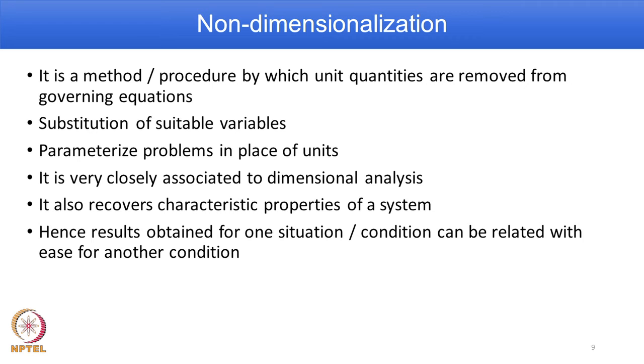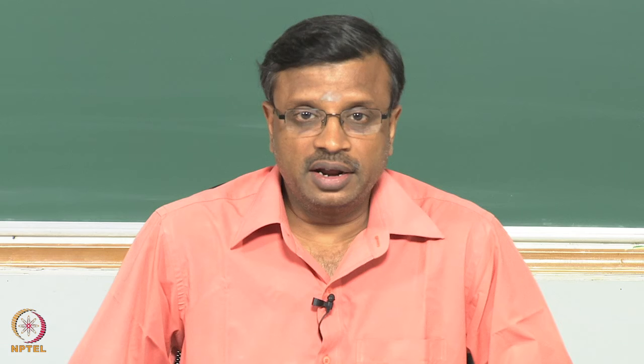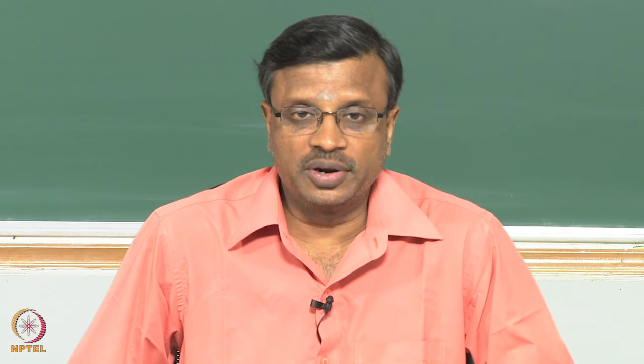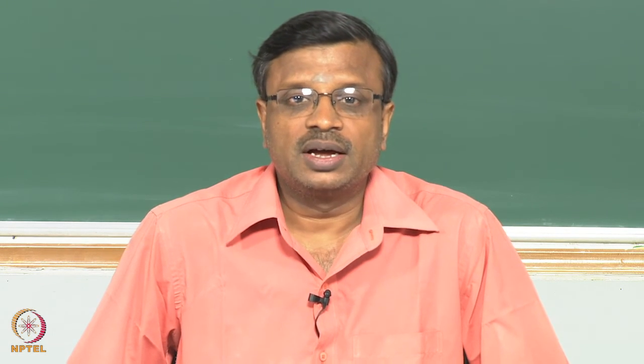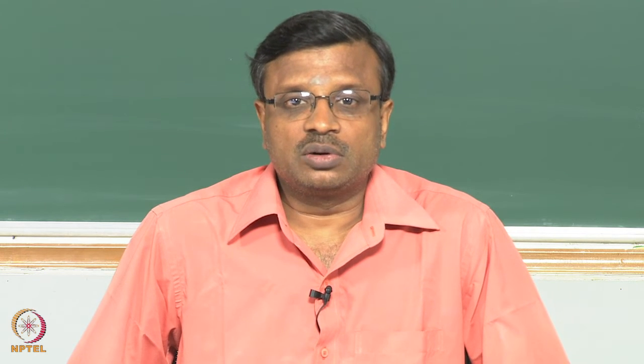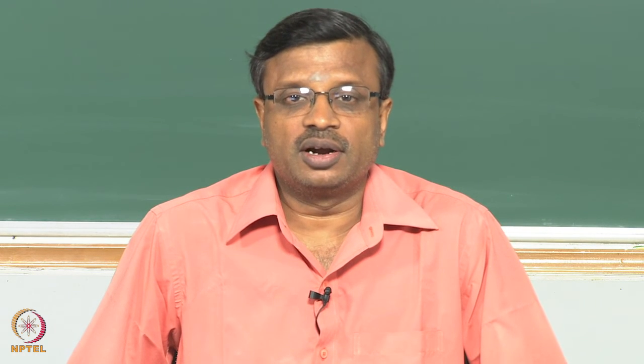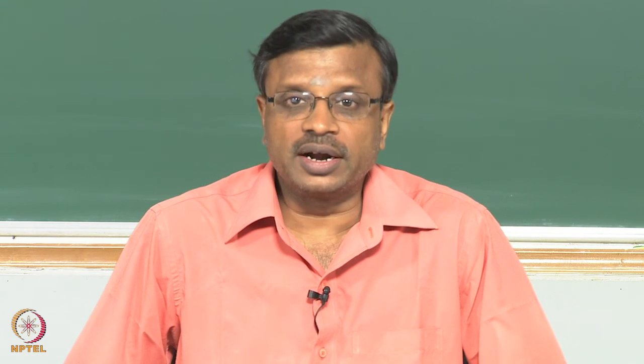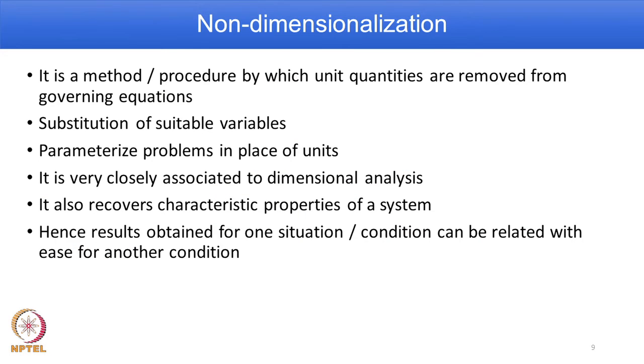Now, another advantage is, suppose you are doing an experiment or running a simulation for one particular geometrical condition or flow condition, and there is a need to repeat it for some other condition. If you do non-dimensionalization, then you do not have to repeat the cases for different situations. Results obtained for one situation or condition can be obtained with ease for another condition.